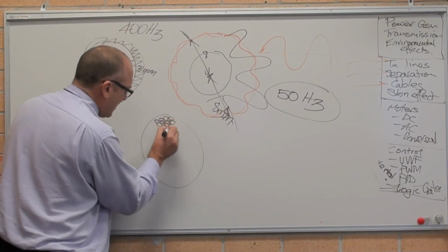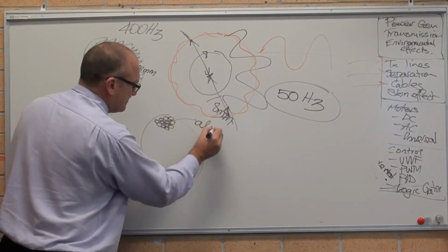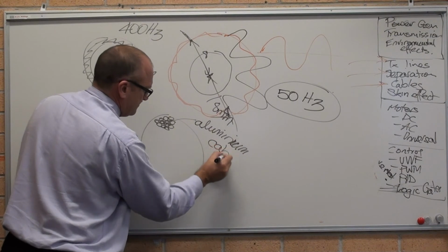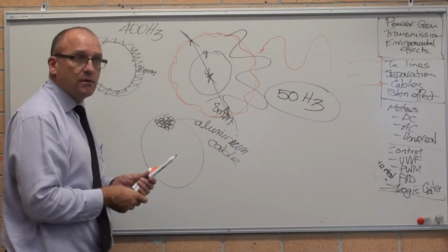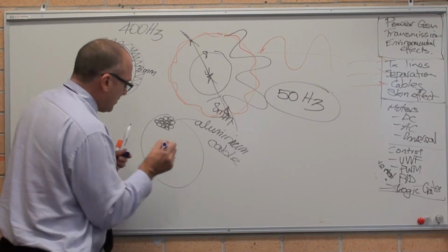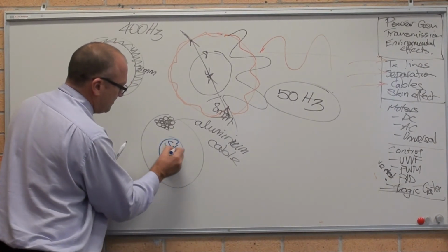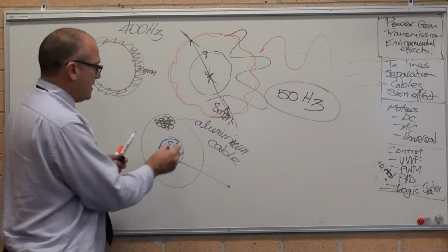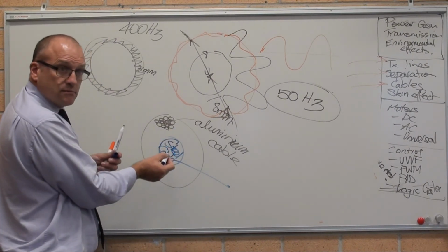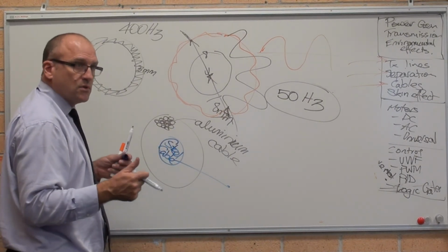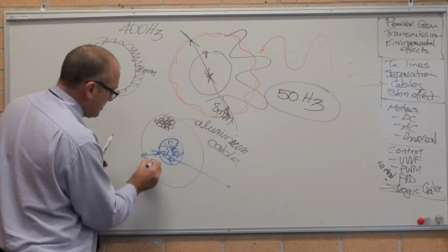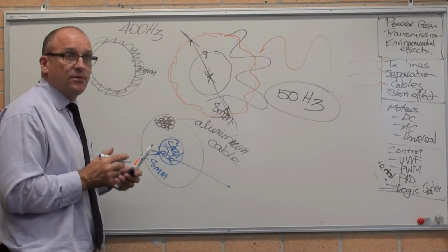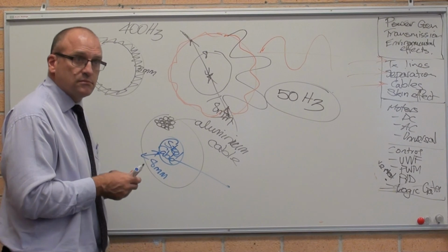So around the outside, they have got aluminium cables. Cross section through a power line. The aluminium cable gives conduction. On the inside, they've got a steel cable, physically for strength. It's sitting on the inside because of skin effect. Make sense? So around the outside, you've got 8mm of aluminium cable, and in the middle you put a steel cable where it doesn't need to carry any electricity. Make sense?